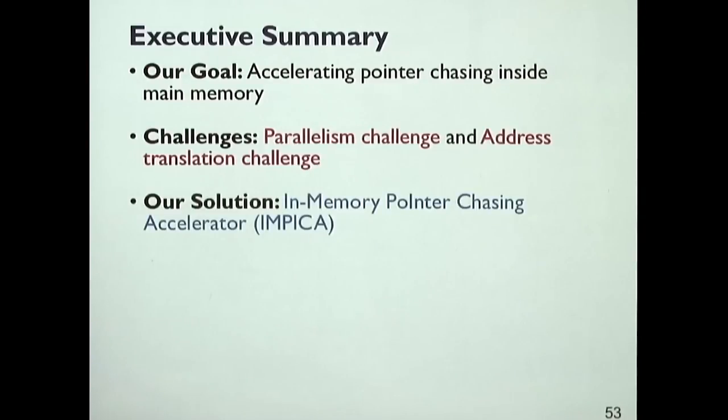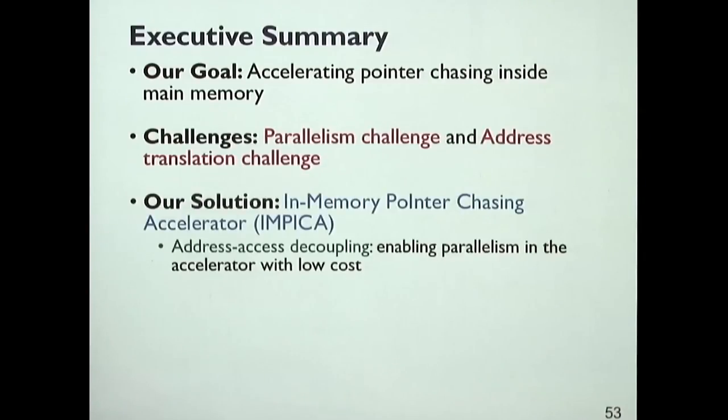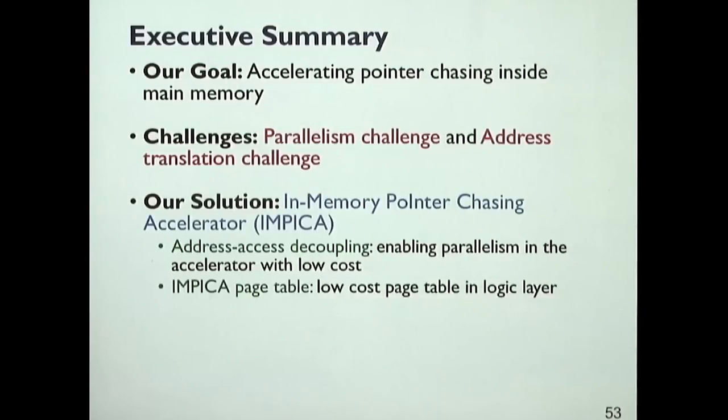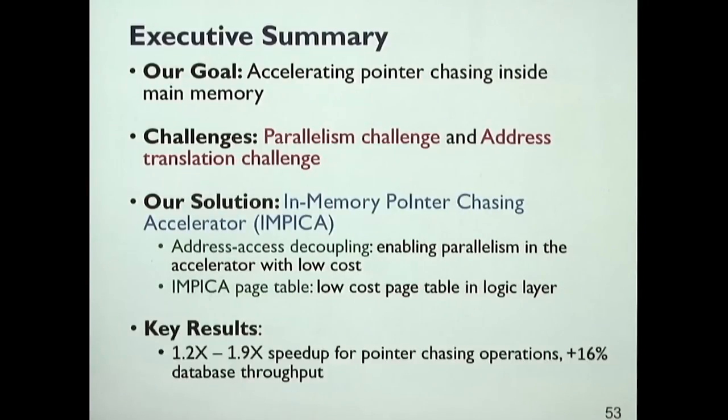Basically, the design is an in-memory pointer chasing accelerator. It's a specialized accelerator. And if your logic layer is reconfigurable logic like an FPGA, perhaps you can put this accelerator inside your logic layer and then take advantage of it. I'll give you the ideas very quickly. One of the interesting things over here is you want to put a page table in that accelerator such that the accelerator can actually do virtual address translation, right? So that you can access a large part of memory. So this solves the virtual memory problem, but maybe there are other solutions also.